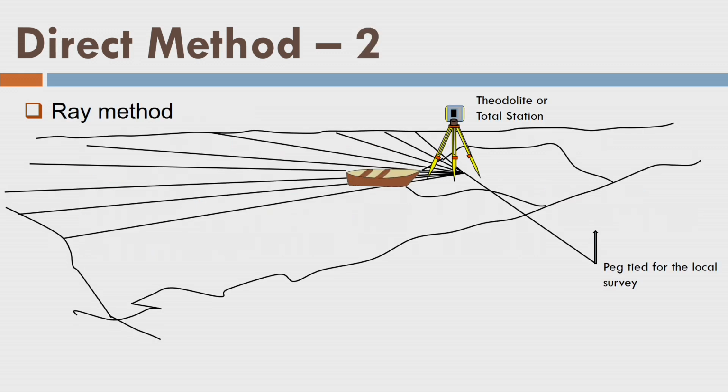Fine. Now let us look into the ray method. There is another method, right? In the parallel line method, I assume that there is a long shoreline and we are stretching one reference line between two reference marks. Now imagine that it is not possible to establish another reference mark, only one. Why? There could be many reasons. Depending on the field situation, sometimes there is no place to establish the reference mark, or there is no way to refer the reference mark with our topographic survey.